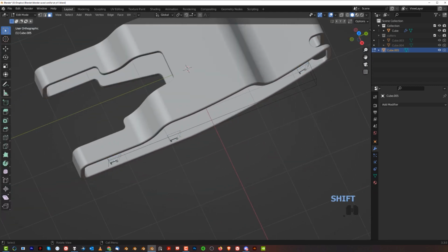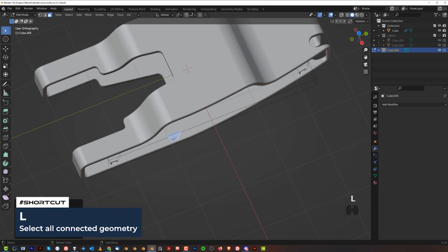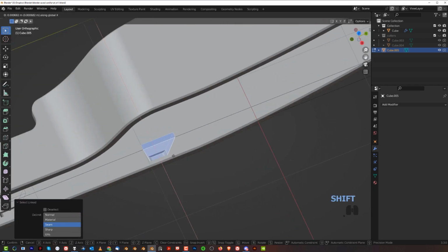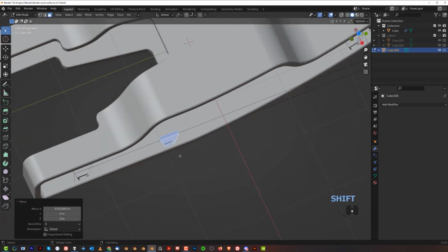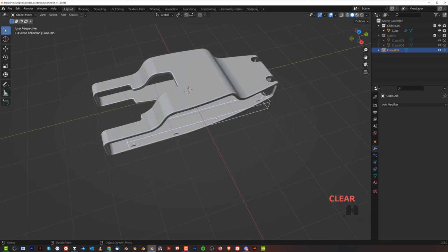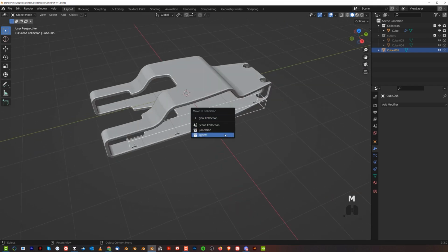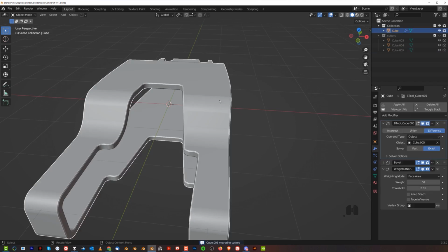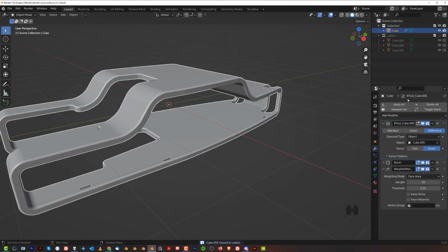Okay. I just want to select this one. Press L, hovering over the shape. And then GX, and move it a little bit here. Cool. And we could move this one to cutters, so M cutters. Then we're gonna mirror this, right? So let's just grab a mirror here.